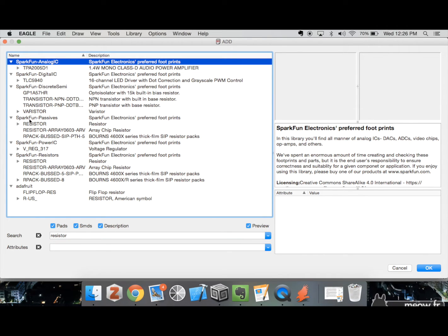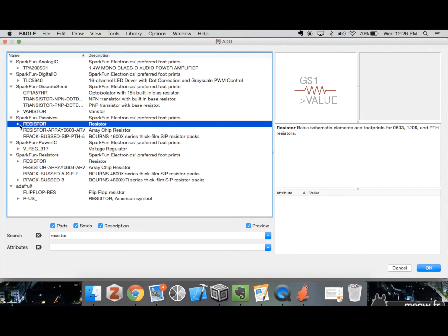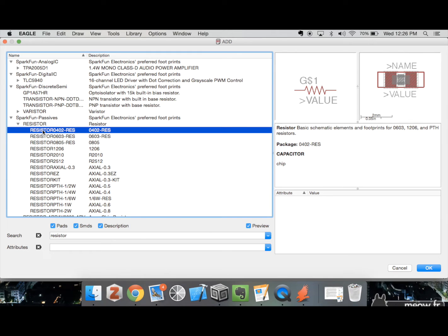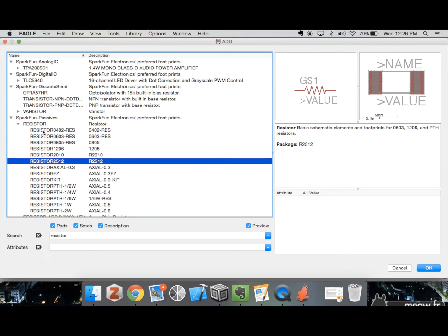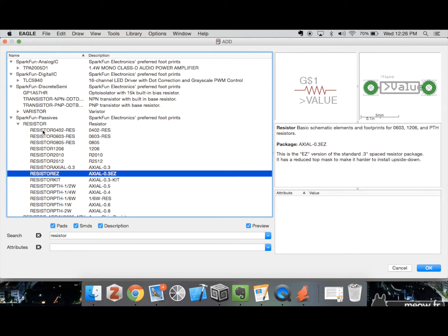Resistor, all right. So I usually tend to use the SparkFun components, but it really doesn't make much of a difference. And I'm going to scroll down these. These ones with the red pads that are kind of square, those are surface mount resistors, and we don't want those. That means that it doesn't have leads you solder through the board. You only solder it to one side. So those are more difficult to deal with, and they're actually not as reliable and fail more often than through holes. So we're not going to use those.